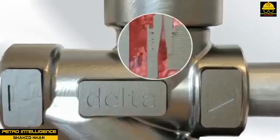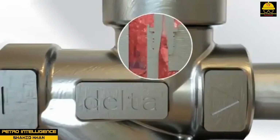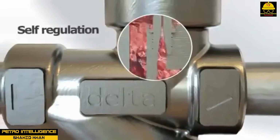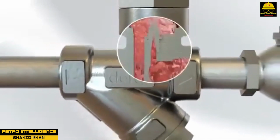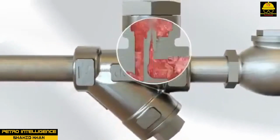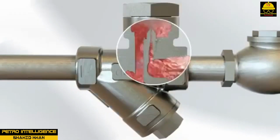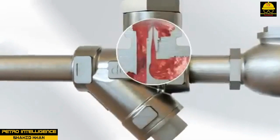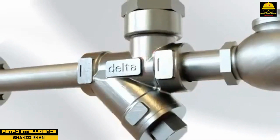Three commonly used types of steam traps are the inverted bucket, impulse, disc or float, and thermostatic, bellows, traps. Steam traps are sometimes considered a special type of check valve. They permit flow in one direction only. In addition, they permit the flow of only certain fluids. The basic purpose of a steam trap is to allow hot water or steam condensate to pass while holding back steam. Steam traps are sometimes used on steam-heated process equipment to remove large amounts of condensate.